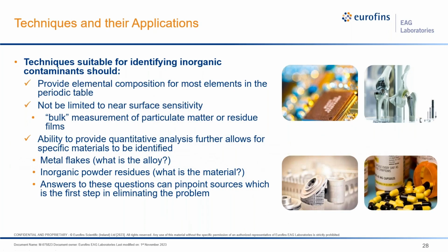So first thing we want to do is figure out which techniques are going to be suitable for identifying inorganic contaminants. And we're going to do that by asking a few questions. One, does it provide elemental composition for most elements in the periodic table? Secondly, is it not limited to near surface sensitivity? So are we going to be able to do those bulk measurements of particulate matter or possibly a residue film? And thirdly, does it have the ability to provide quantitative analysis, further allowing for specific materials to be identified?